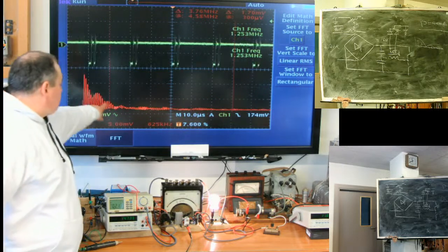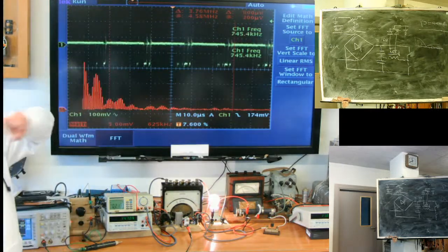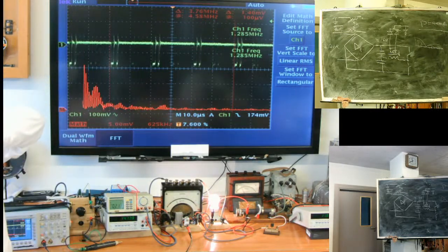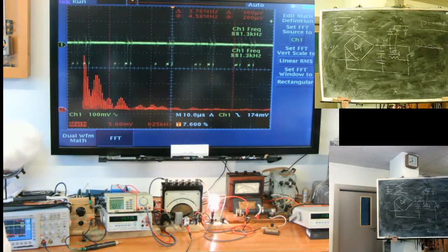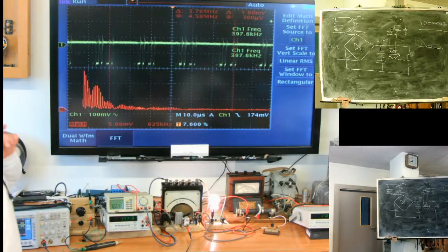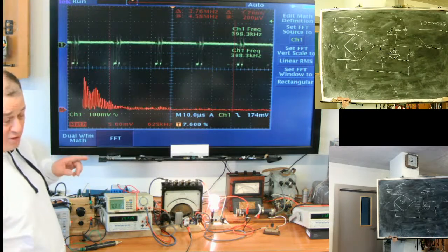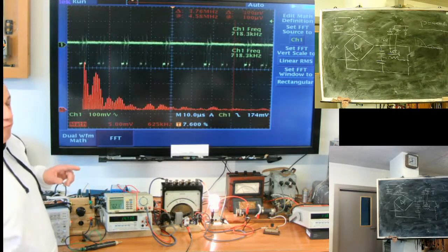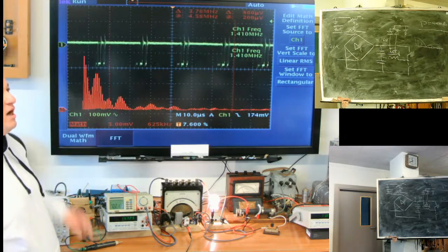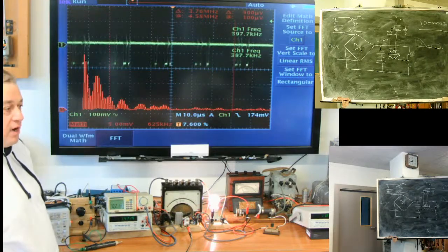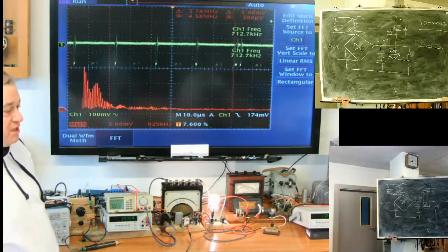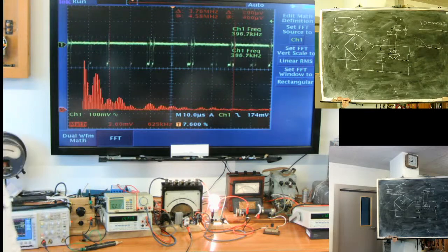And you see the spectrum, how it widens. It's all the noise you will get for your schematic. There are many cases people caught: what a strange signal, look, I have a signal from outer space. Idiots, it's your power supply.